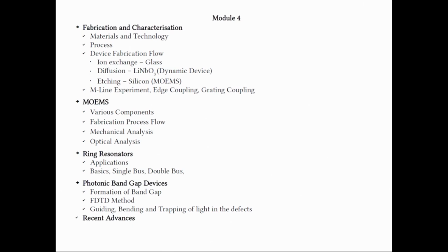So the resonant frequency is a very sensitive function of the radius, the bus waveguide, and the gap between the bus waveguide and the ring resonator, and so on. Ring resonators have many applications. In particular, they can be used for optical communication filters, and we have seen examples of a comb filter in this course, where you have rings of different radii and a common bus, with bus waveguides to tap the output, and we found that they provide a very sensitive function for different frequencies of operation.